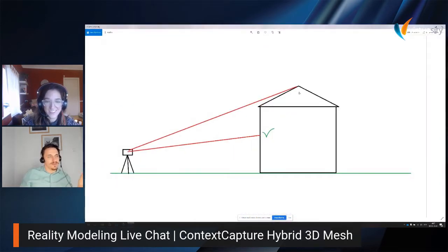So what's the problem? The laser beam has its angle, just falling on the surface, and in case we are, for example, scanning a roof, which will have a rather small angle, then as you see, this is really simple, of course, I just used Paint for a really simple representation. We're going to get a really sharp angle of the laser beam, which hugely affects the accuracy of the measurement. First of all, the laser beam is going to be kind of splashed on the surface. Then the reflection will be much higher. The noise is going to appear.